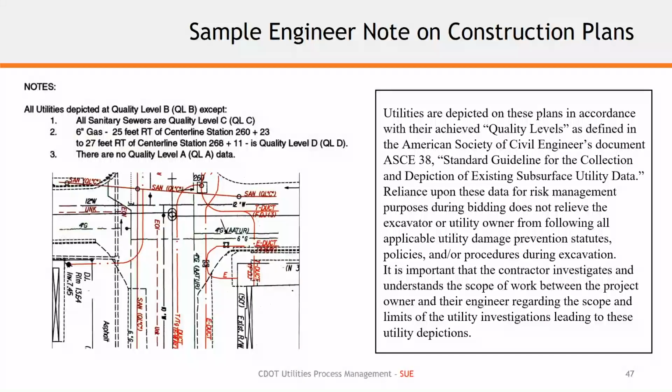So there are separate things going on here, but it's intended to emphasize that the SUE investigation is a standalone piece, and that the excavation is also a standalone piece. I just want to make sure that's clear, that contractors still must complete their investigations based on the requirements under the excavation portion of the law.